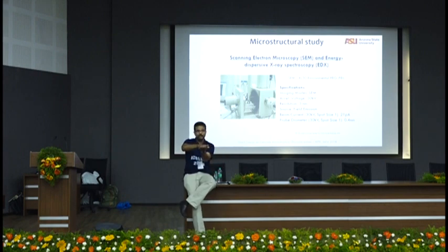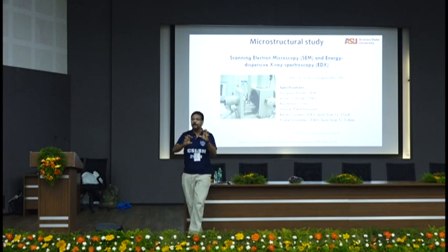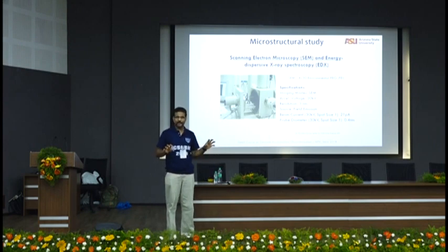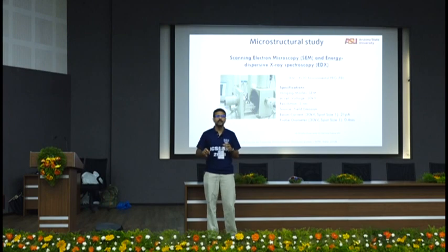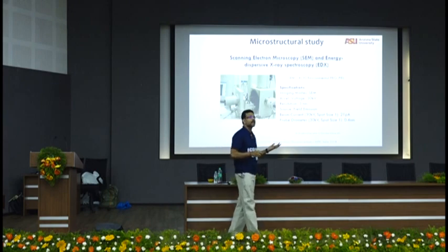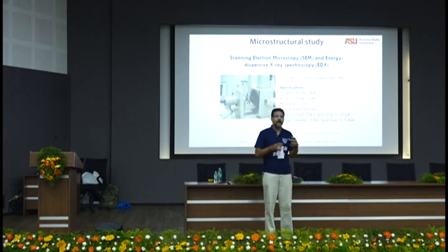In a 2D structure, you have a lot of quartz, right? Quartz, or silica, will be coordinated with a lot of different things, right? Silica will be coordinated with alumina. So based on the coordination of silica with different things, you call different silica structures like Q1, Q2, Q3, Q4. It's the coordination levels of silica. So you find out through NMR how much of each of these coordinated silica are there.